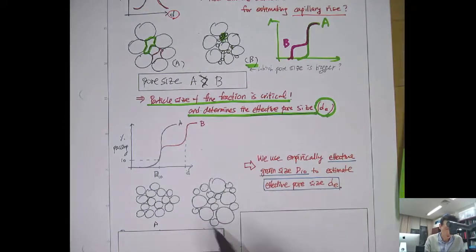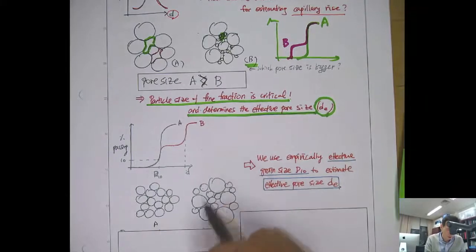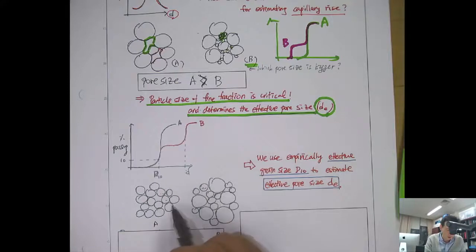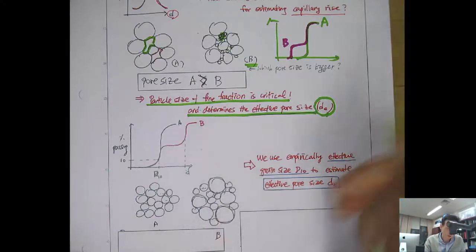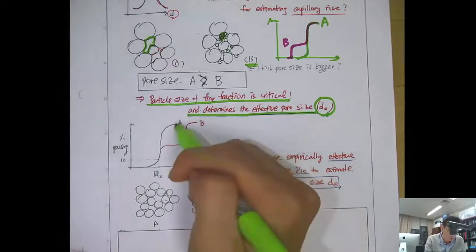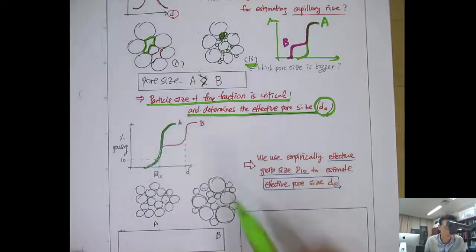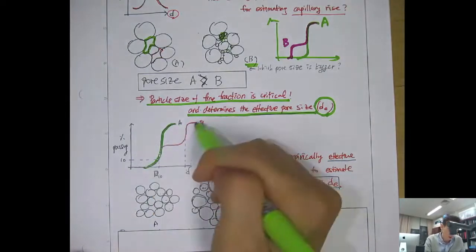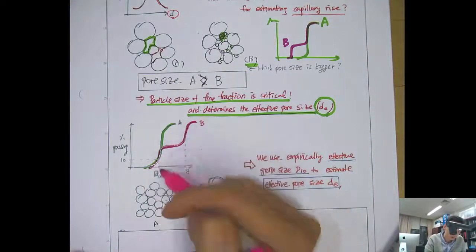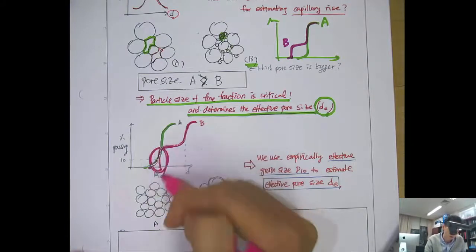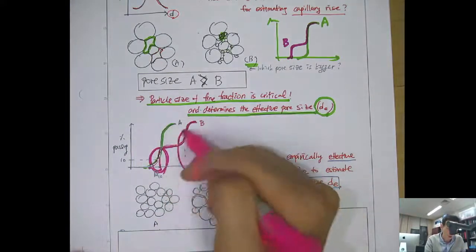And this is soil B. It has the same small particles with the same diameter as A, but it also has large particles like this. When you plot the particle size distribution, you have this one for soil A and this one for soil B. It shares the small particles, but B has larger particles too.